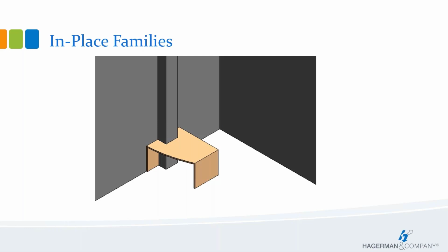Now, I know some of you might be cringing a little bit. I'm going to interject some opinion at this time and say that I recommend never using these, and I wouldn't make a statement like that without at least explaining why. So the first drawback is that these families are stuck inside the project environment and cannot be saved back out to your library or modified in the family editor.